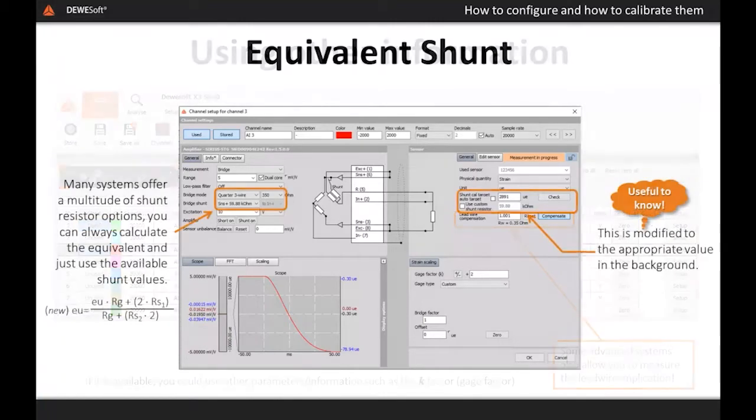From time to time you may encounter a sensor that has a shunt value related to a calibration performed on the sensor by the manufacturer. This is one of those moments where it would be nice if everyone agreed to say 174.5 k-ohm shunt was the standard, but alas they don't, and they probably won't, so here are some solutions.